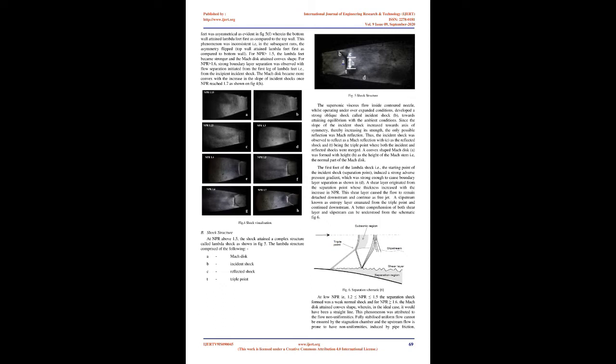3. Experimental analysis. A. Shock visualization. The flow field inside the contoured nozzle is a function of NPR. Schlieren photographs of the flow field with increasing NPR, captured using a vertical knife edge, are shown in sequence in Fig. 4, A to H. For NPR 1.15, the nozzle was not choked and the flow downstream was subsonic, as indicated in Fig. 5, A. For NPR equal to 1.2, weak normal shocks were observed downstream of the throat, as shown in Fig. 5, B. Above NPR 1.3, the existence of the normal shock was more prominent.